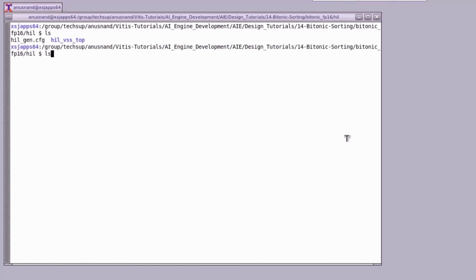Two key files are generated by this command. HIL_interface_spec.json will be used by our MATLAB host application to define the design's ports. SD_card.image will be flashed onto an SD card for use with our dev board.